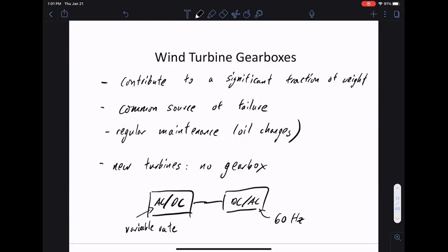So our goal is to go through the different types of machines. The last one we cover being this one with no gearbox at all. But we'll start from the simple ones to get to here. And this one is becoming popular because nowadays finally the power electronics caught up with the gearboxes. It's cheaper, it's more reliable. It's definitely lighter weight than gearboxes, so that's why this is winning. And this is the trend we're seeing out there. So that's something to keep in mind.